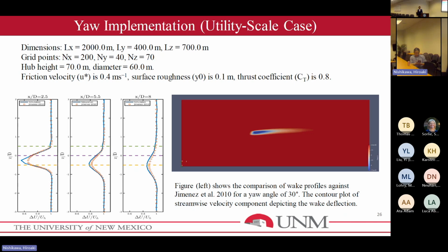We didn't do this kind of quantitative analysis, but what happens is, for the mean velocity profile, if you just take a couple of flow times, it gives a statistically uniform profile. But for the higher order statistics like turbulence intensity or skewness, you need more time averaged data. But as long as you have around 70 flow through times, it gives a statistically homogeneous flow.